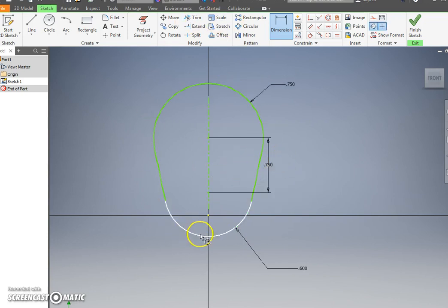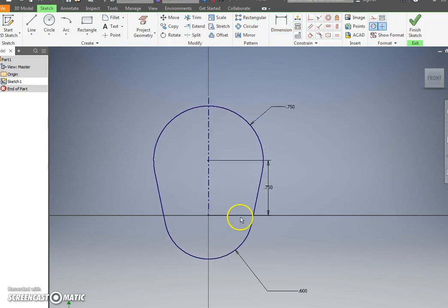So now my object is made. But I want it to be all purple, that way it's totally constrained. Like I've said, that's not always a must, but it just kind of helps things out sometimes. So I'm going to drag the middle point here down to the bottom. And now I realize why none of this is working. Oh, there we go. Now it's locked in. Okay, just grab this dot and move it down. It doesn't matter if it's on the line or not. So there we go. Sorry about that.